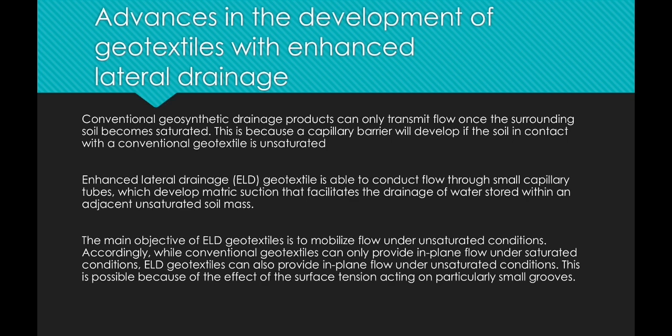ALD geotextile is able to conduct flow through small capillary tubes with developed matric suction that facilitates the drainage of water stored within an adjacent unsaturated soil mass. The main objective of ALD geotextile is to mobilize flow under unsaturated conditions.